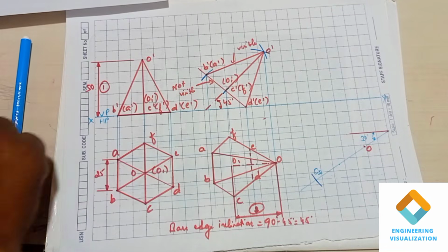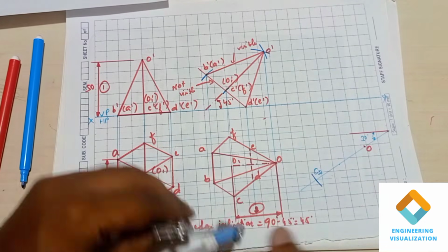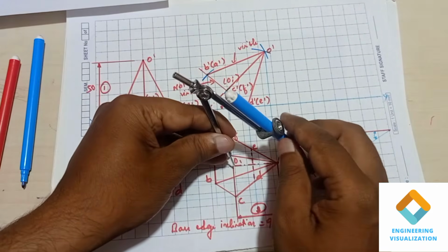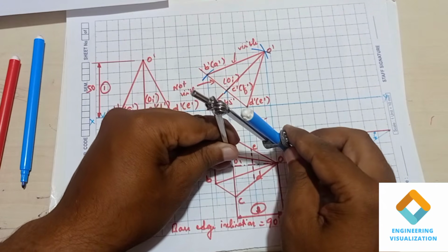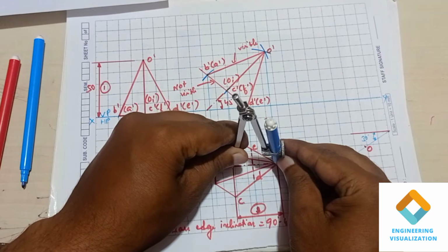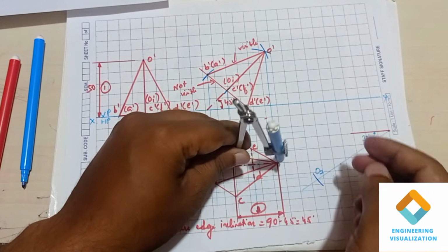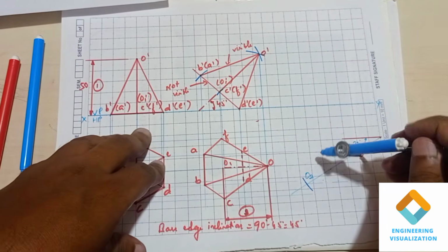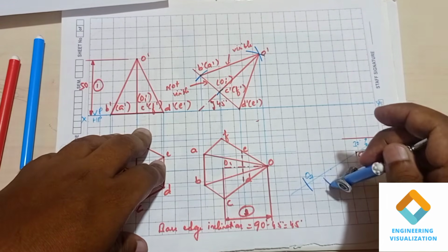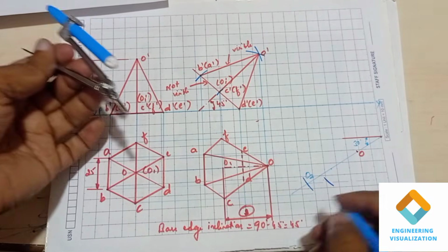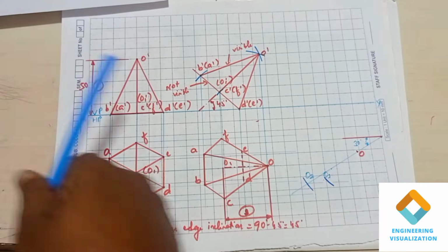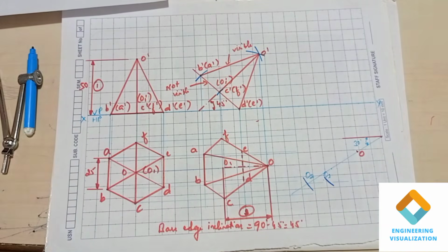Okay, now the second length we have to measure is from O to O1. That is what I have marked as 2, right? This length we have to measure from the compass. Okay, measure this line, keep it at the reference point of O and cut the arc. Join this cut arc point and you can mark this as O2, sorry, O1.